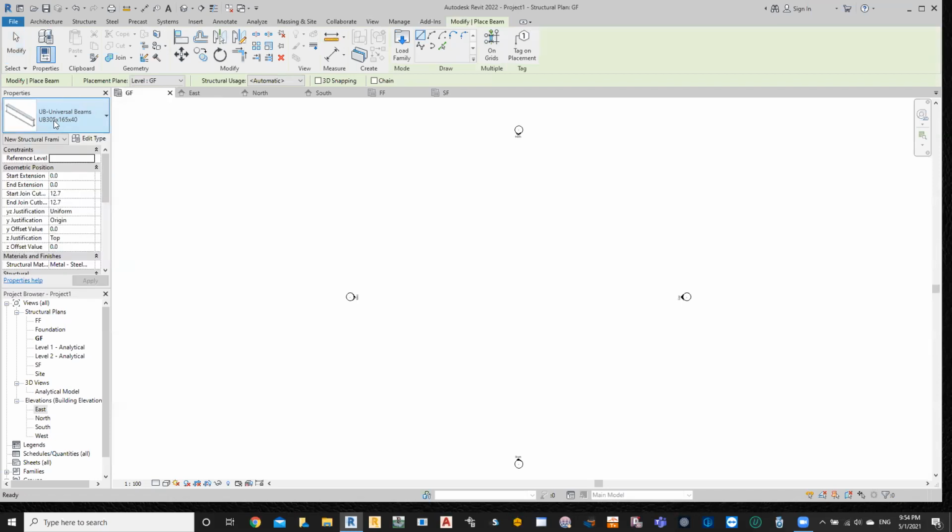You just model it and change the section later in Robot, since it's much easier to change over there. So you just need to model it here, shift it to Robot, and later change the section sizing in Robot, and I'll show you later how. It does not matter what type of element you are having.